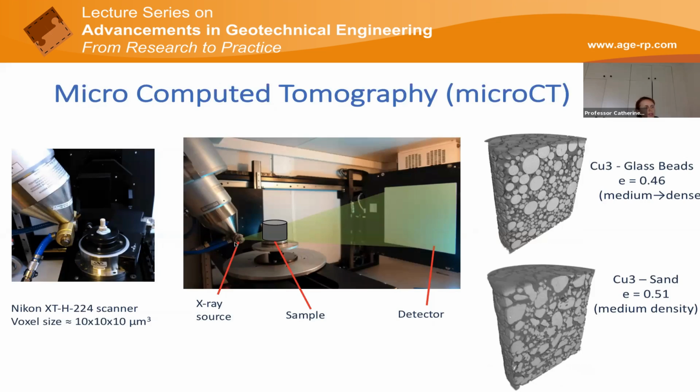We then take that core to what is called a laboratory microCT system. So here we have an X-ray source. We put our sample on a stage and we have a detector. The source passes through the sample and it's recorded on the detector as a radiograph. And that image is the same as the X-ray image you'd get if you broke your arm and had an X-ray in the hospital. But what then happens is after taking that image, the sample is rotated a small bit, maybe by just 1 degree, and another radiograph is taken. And then the sample is rotated again, and yet another radiograph is taken. And there's a full rotation of the sample, maybe through 360 degrees, maybe through 180 degrees, depending on the setup of the particular microCT apparatus. But you get a stack of X-ray images.